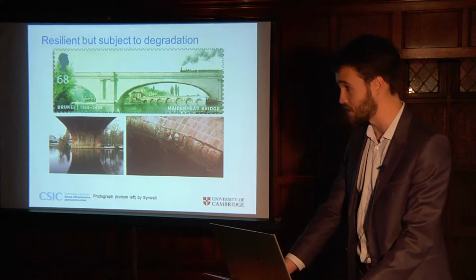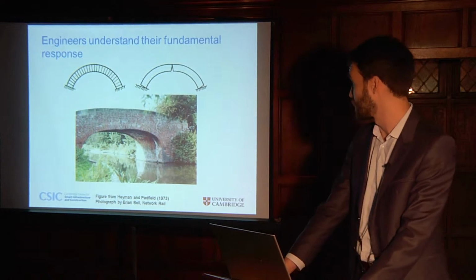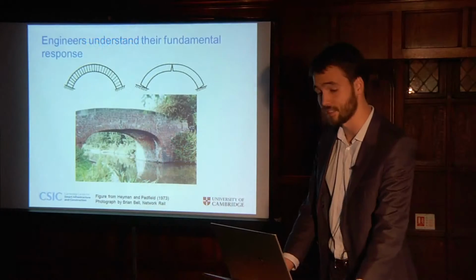But fortunately, as engineers, we've developed a good understanding of how they respond. For instance, when a masonry arch settles, we know it formulates hinges and we know it cracks. We also broadly understand its long-term response, which is affected by rail loads and water ingress.